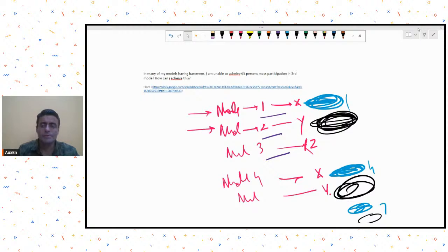Maybe adding more walls, more shear walls, distributing them near the periphery, adding some L-shaped walls in the plan, or removing the central cores and replacing them with some column beam framing. These can be some of the ways to do it. But I don't have a ready answer.